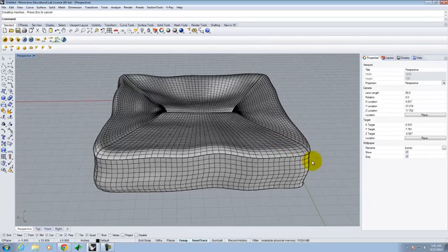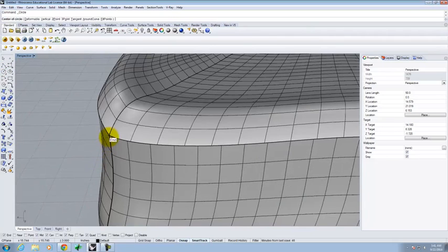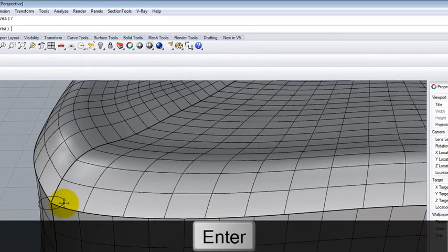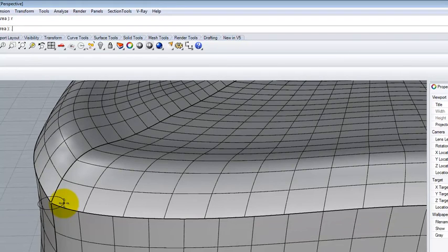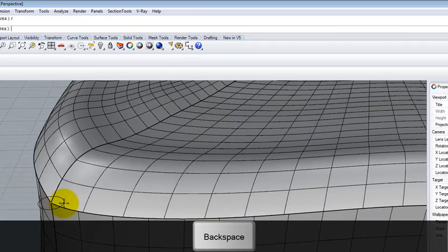Okay. Now, sometimes you want a little bit of extra trim, or there's a little piece of piping or something that follows along. You guys have all done this already. If I create a little circle, let's do a radius of, what should we do? A 1/4 inch is a little thick. Yeah, 1/8 is a little small. Yeah, let's do 3/16. See how that looks.